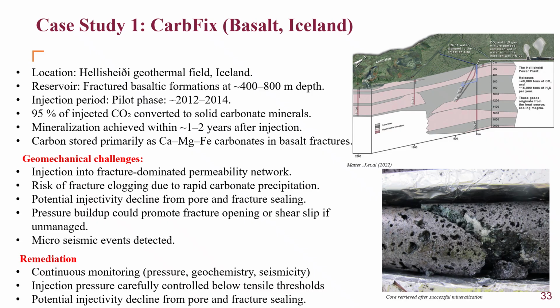One is the CarbFix in Iceland, where CO2 was stored in a fractured basalt formation at a depth of 400 to 800 meters deep. The injection started in 2012 and ended about in 2014, and mineralization was achieved in those 2 years.